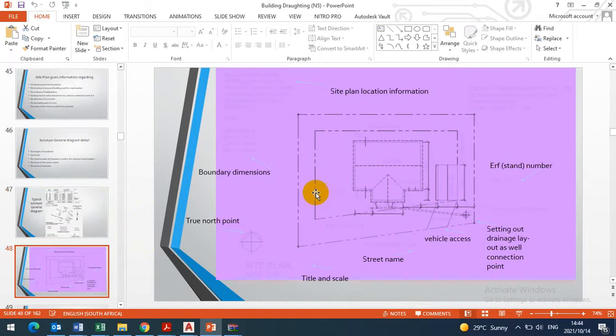We talked about this site plan. When they give you a site plan like this, with these dashed lines, first we start with the property line, then you know how to draw the building line. Then there's a house and the dashed line, which is the roof edge. This is the roof, a gable end roof, which slopes on this side and this side. This is the ridge, sloping on two sides. This is the type of roof we call a gable end.